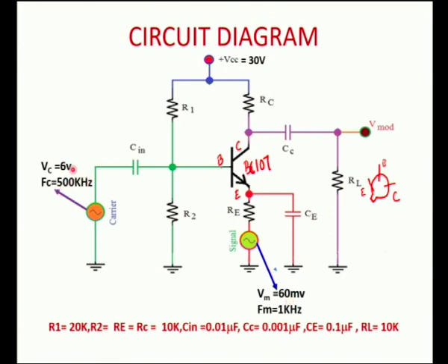So, and also the frequency should be more than hundreds. The relation between the frequency of the carrier and the message should be, FC should be at least 100 times FM. So, for a small example we can have this to be 6 volts and this to be 500 kilohertz. Now we have completed all this part, right, and the output AM modulated waveform